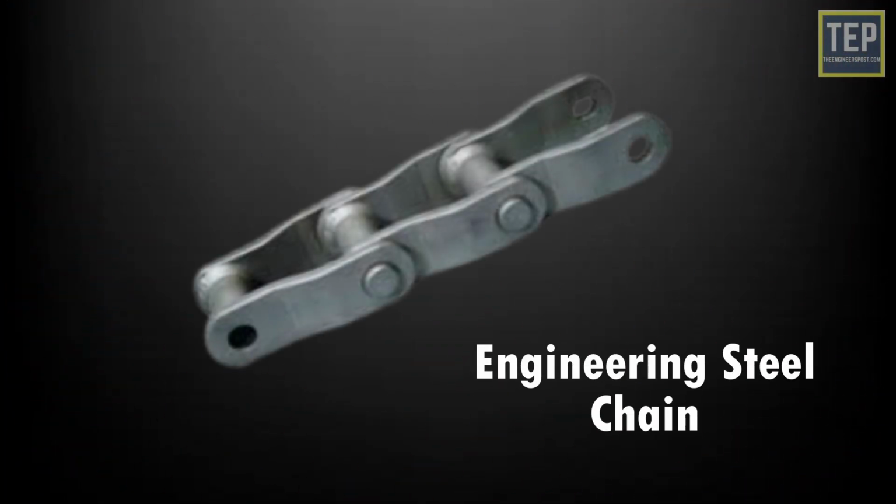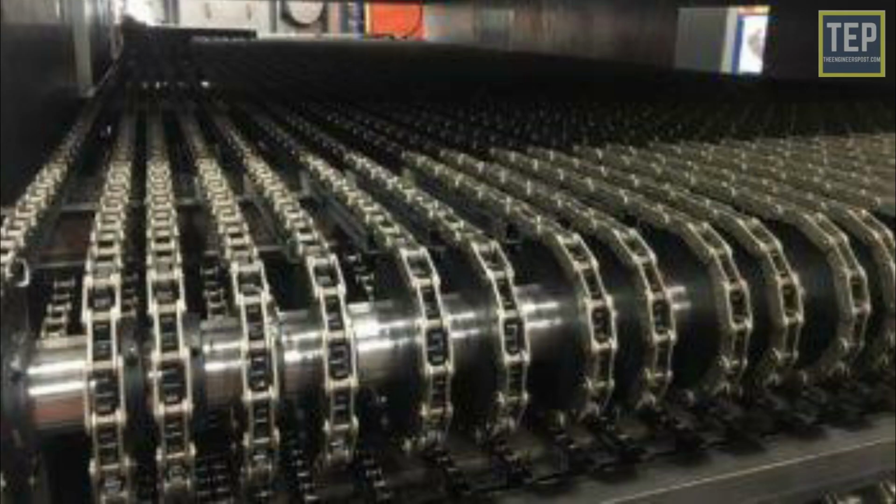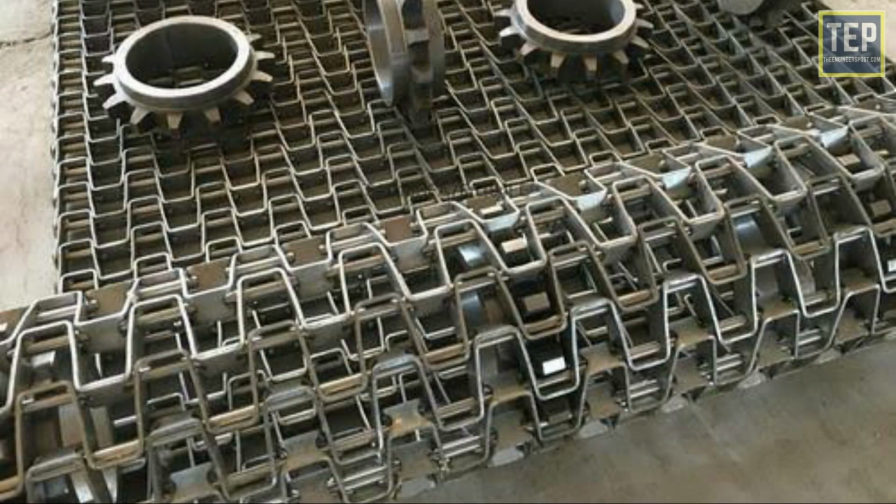Engineering steel chains were first developed in the 1880s, and were designed for difficult conveying applications. Most engineering steel chains are used in conveyors, bucket elevators, and tension linkages. Only a few are used in drives. The main design considerations for these chains are tensile loads, several types of wear, lubrication, and the environment.